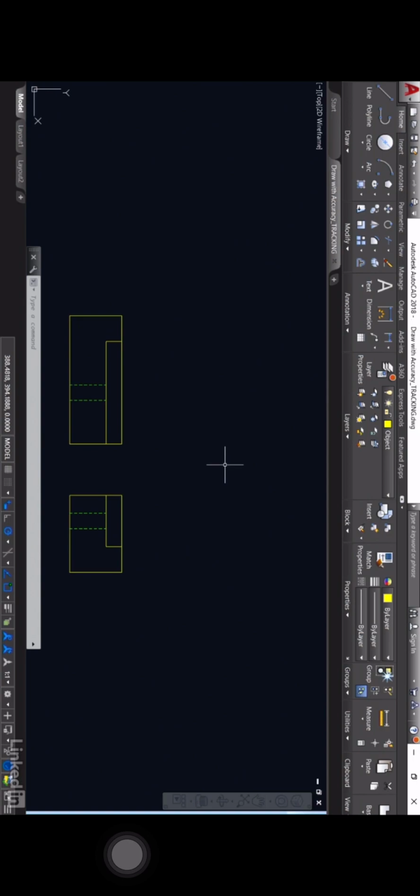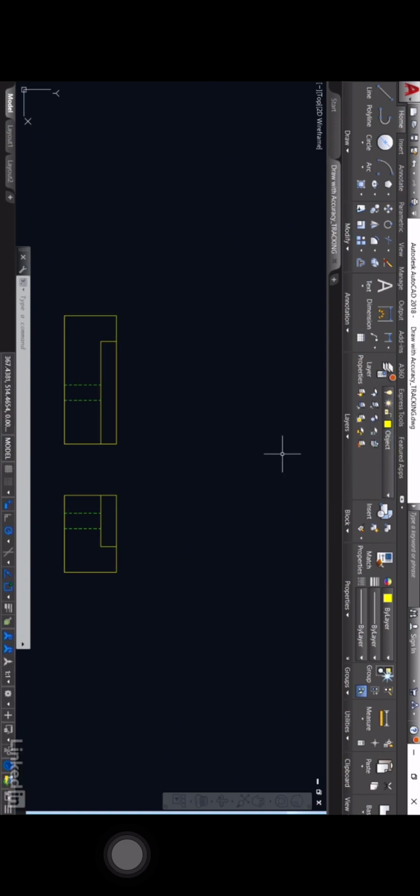Now the lovely thing about object snap tracking is it allows you to take up to 7 points concurrently and track them without having to draw construction lines. It's very quick and easy to do. So just make sure you're on the object layer initially. You can see that in the layers panel there on the home tab on the ribbon, in the little drop down here. Just make sure you're using the object layer like so. Now, I'm going to go down to the status bar and check that object snaps are on. Object snap tracking obviously is on, but also check that your polar tracking is on. It's always useful to have that if you need an angle to measure a line against as well.